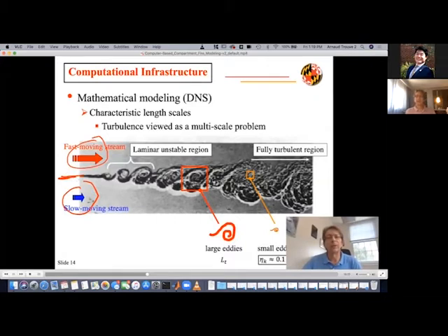You have a mixing layer that develops an interface between these two flows that are developing parallel to each other, but because of the shear between the two streams, because these two streams are at different flow velocities, the shear will create an unstable mixing layer that eventually will transition to a turbulent flow.